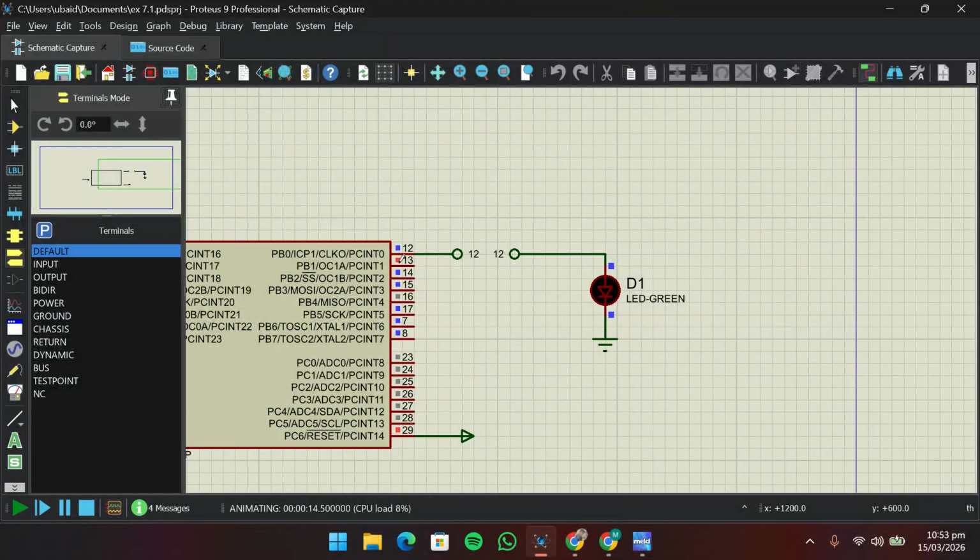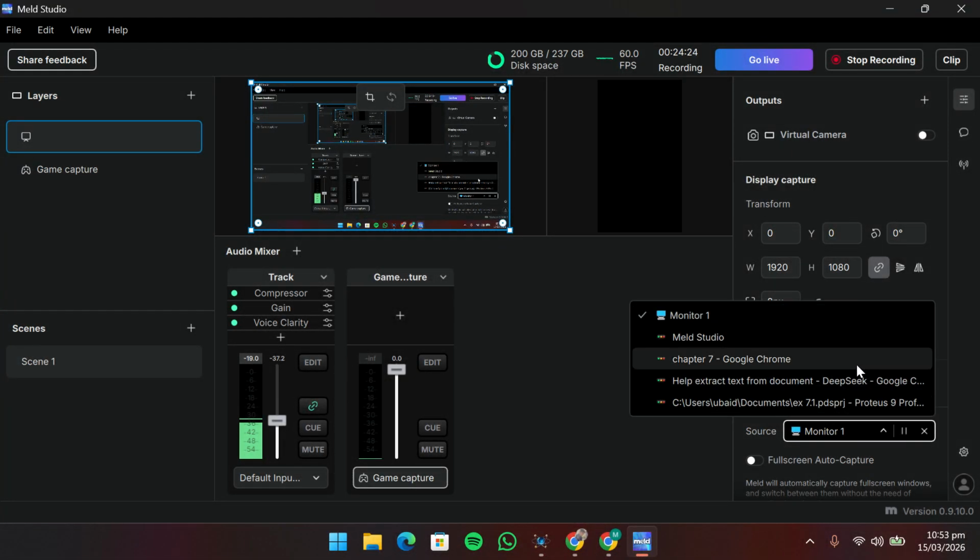We can see that it has moved towards pin 13, and now both of them have turned on. So now it says 2 in binary, and now it says 3 in binary. Now it says 4 in binary, because 4 means 0000 0100. Now it is going to go towards 5, which is 0101, and we can see that it is basically replicating the binary code here. So this was 7-9. Let's move on